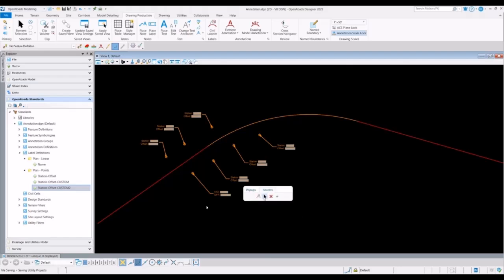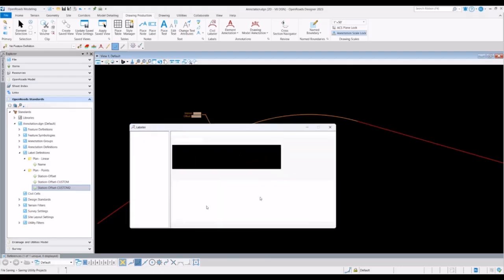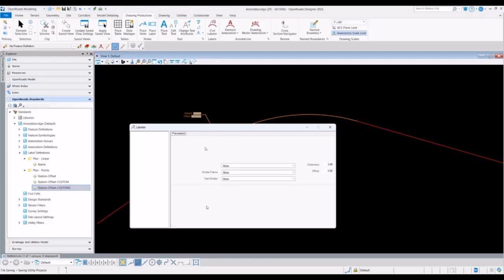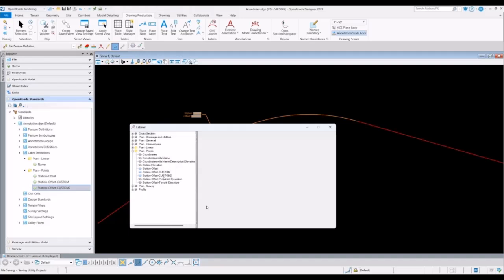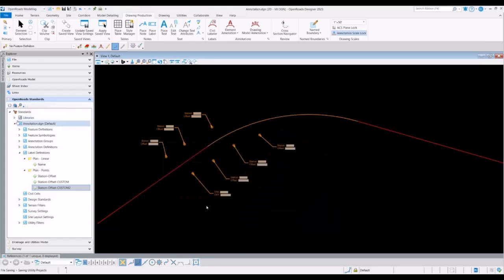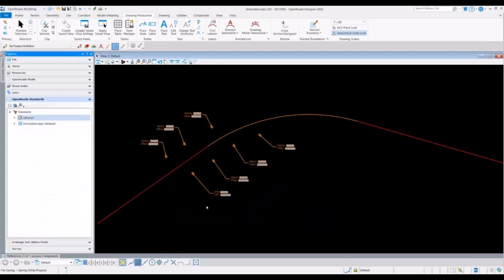All right. There's the pop-up menu. So in my active view, hitting the space bar, I can kick off the civil labeler command rather than having to move my cursor up to the ribbon. Incremental time saving, but still time saving. You can see in the tool there's the quick custom, quote unquote, civil labels that I just copied from the Explorer, already exposed.